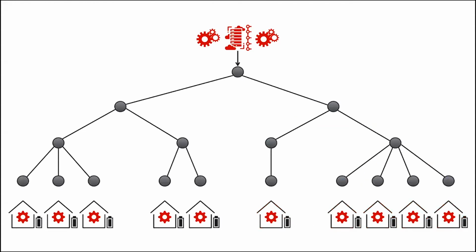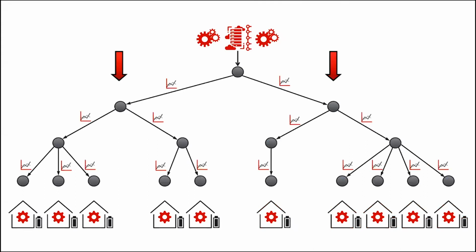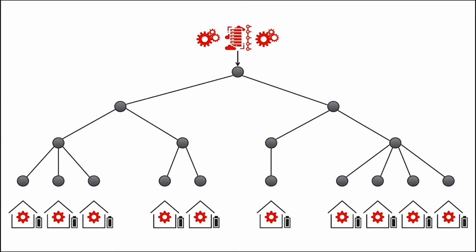Another way we can control is to take advantage of the edge computing platform. So for example, we can distribute time series forecasts for energy prices or weather and run the optimization at the edge. And one advantage of the distributed optimization is scalability. We don't have to solve a huge optimization over all sites. And the other advantage, which also applies to direct control, is resilience to the inevitable intermittency in communication. So if sites go offline for short amounts of time, they can operate autonomously. And if sites go offline for longer, they can revert to purely local optimization, which still provides value to the customer.